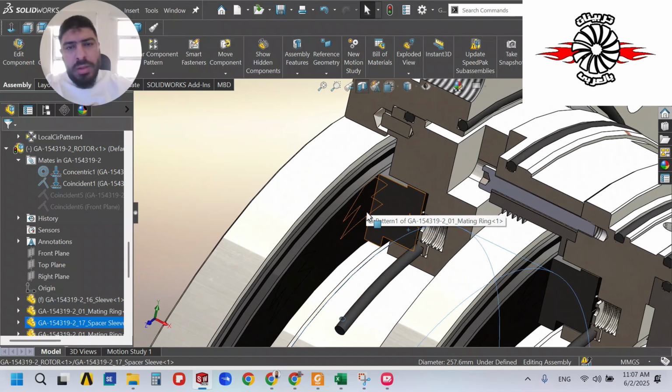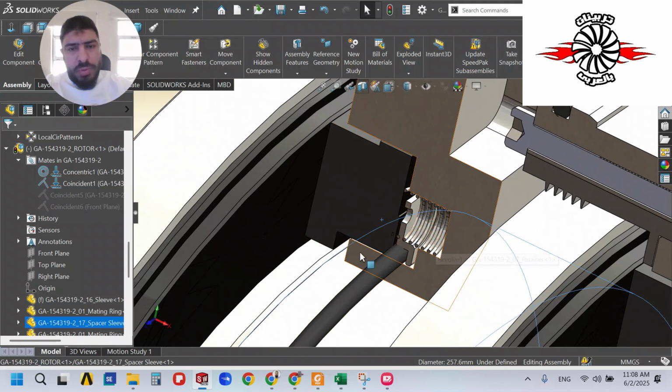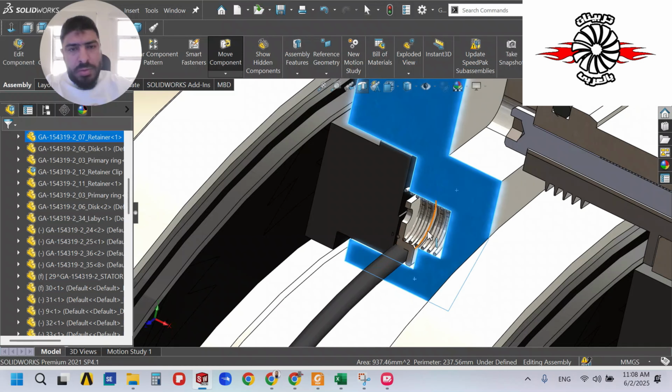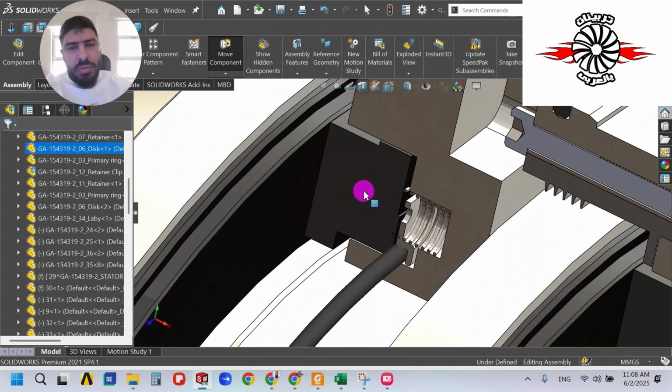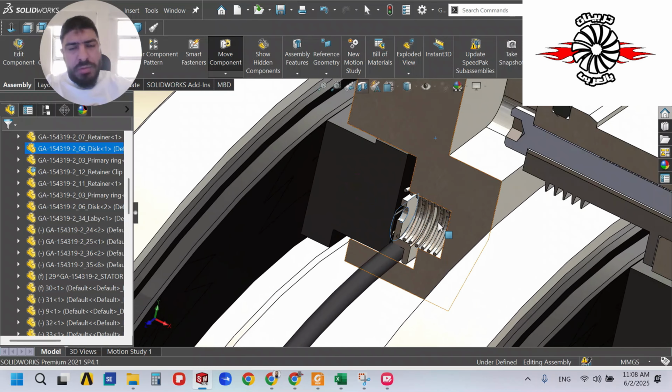It will act on the primary ring, and this layer of gas, between 3 to 5 micron, will try to lift and keep away the primary ring and keep this gap of 3 to 5 micron against the closing force by the spring. So it will try to keep the gap, also against the closing force of the spring itself here.